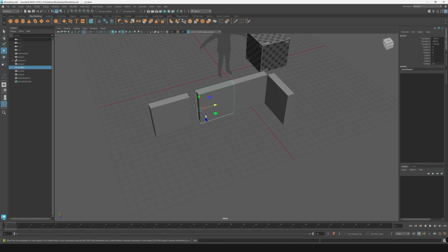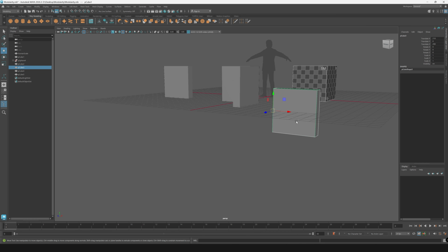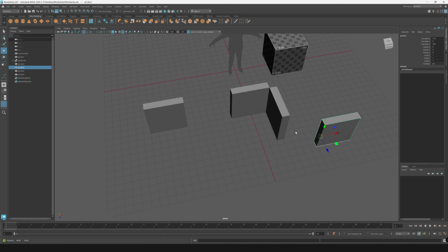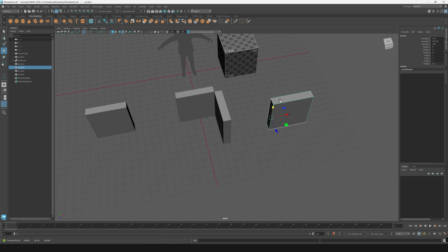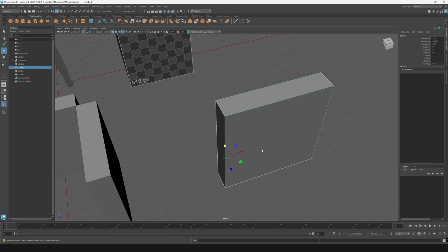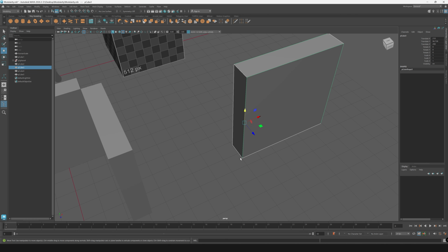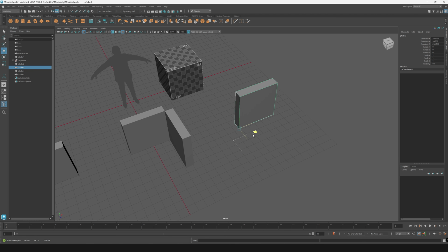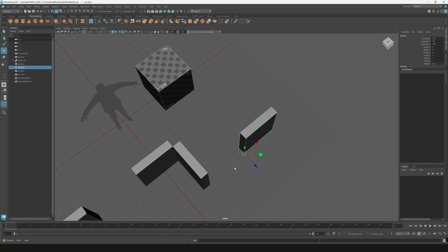And right now, if I were to drag him in, he's going to drag like this. And that's not what I want, because he's like halfway through basically. So how do I want to approach this next? Well, we've already moved our pivot point in 2 different directions already. Maybe why don't we connect the pivot point to the bottom of the object, so that when he gets dragged in, because again, he's going to get dragged in and placed on whatever ground surface at the pivot point's level. So if I do that, he's going to hit this ground like this, like that. Exactly.